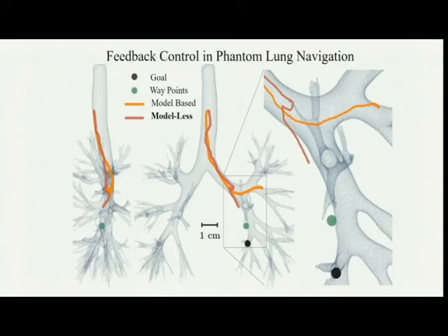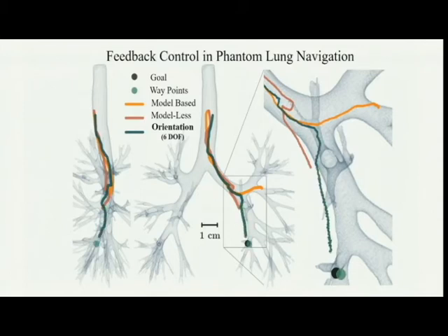So it essentially fails. And again, this is where we're using just the orientation part of the model, it doesn't scale any of the elements of the Jacobian. It doesn't think you need to pull too hard or too light. It always keeps that scaling fixed, and so it doesn't get stuck in the same way that the model-less control does. And again, I mentioned there were two ways that we have of doing this. One, assuming you have a 6-DOF sensor, another assuming you have a 3-DOF sensor, and they both reach the goal point here.